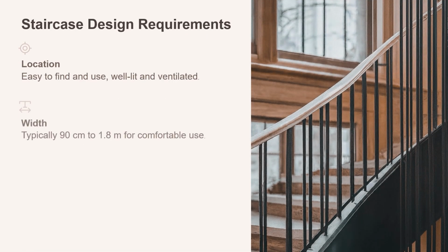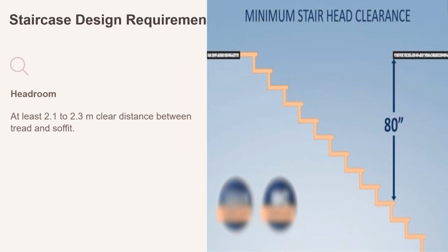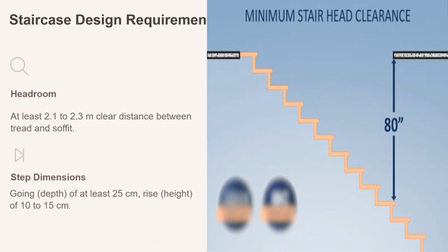Sure, let's now understand the requirement for designing stairs. There are 6 main requirements. They are location, width of stair, length of flight, pitch of stair, headroom consideration and step dimension.